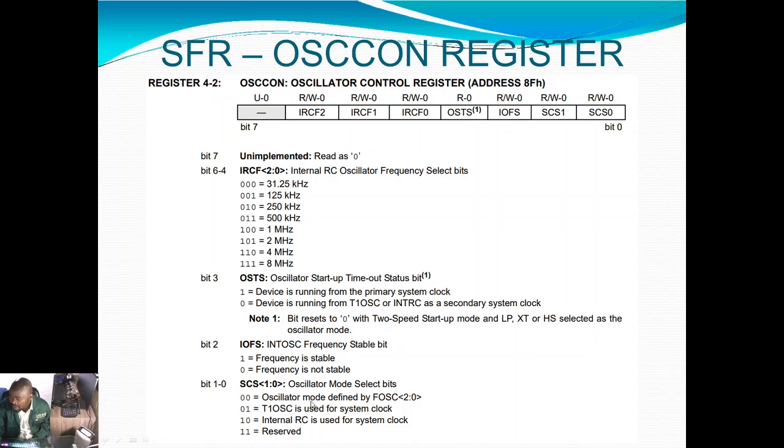And now the oscillator configuration, where our oscillator is going to come from. Because in the configuration bits we said we're using the internal oscillator, let's assign this to the configuration bits, and then the configuration bits will say we are still using the internal oscillator, right? So we are assigning the selection of the oscillator to the configuration bits, which already assigned the internal oscillator. So our number is going to be 6, the 4 upper bits, and then 1, 1, 0, 0. 6C.